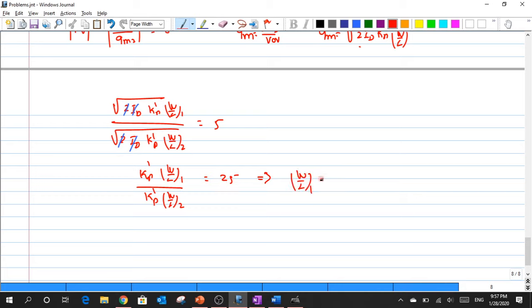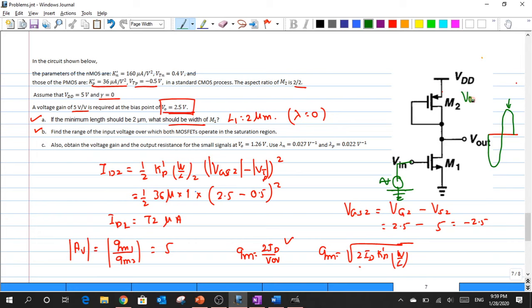Now, whenever there is a swing across the input, I will use even the bias circuit here. This swing in turn creates a swing around this Q point at the output. So a swing across my input Q point would create a swing across my output Q point at the output. Now how far can this V out go up such that my transistor stays inside the saturation regime? From the theory, we got to know that this value, my VO max, is supposed to be equal to VDD minus the threshold voltage of this particular device, which is nothing but my VTH.